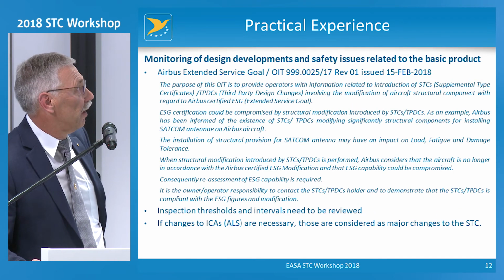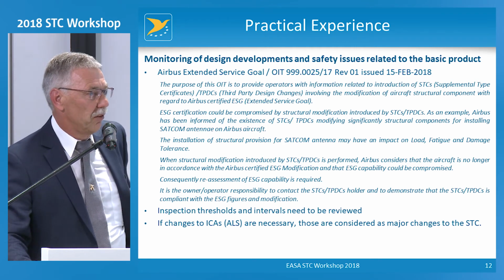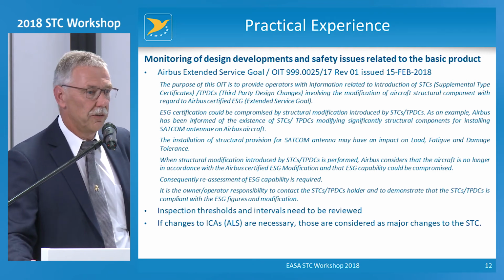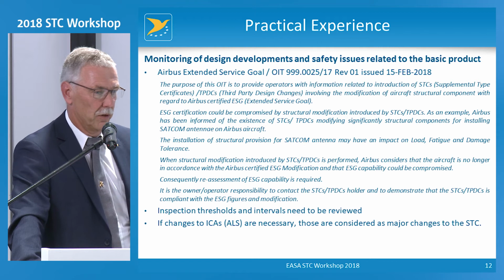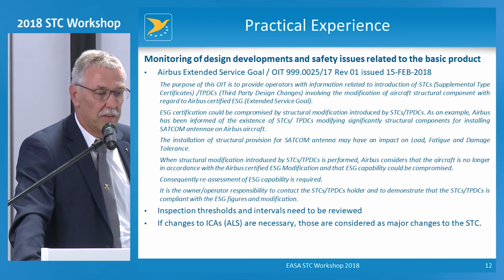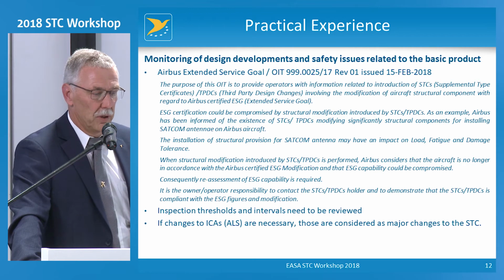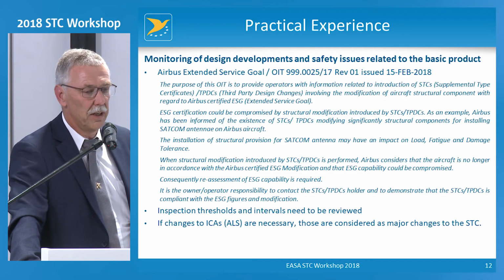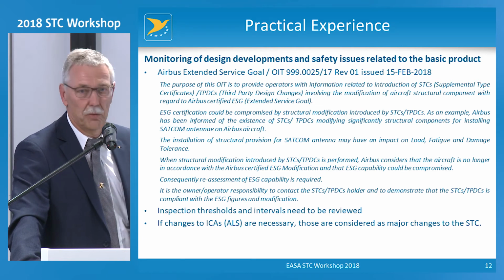One thing where monitoring of design developments is important, and this is an example from the Airbus A320 fleet. Airbus did an extended service goal certification to come to a higher limit of validity of the overall aircraft to fly it longer. And some of the repairs and Airbus major changes and so on have been reviewed, or in principle it was a comprehensive review. They did additional fatigue testing and everything to show that their design is safe for the ESG, even when repairs are made and so on.